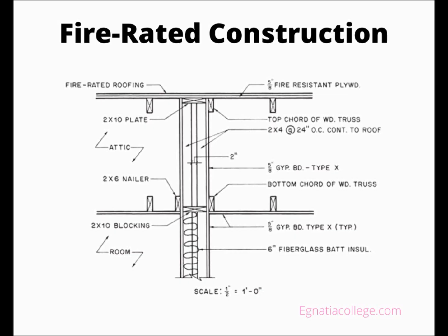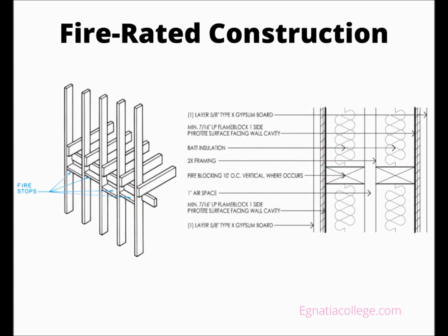To separate the housing units, a fire-rated party wall should extend all the way from the foundation to the roof. Most building codes allow an alternative to extending the party wall through the roof. The fire-rated construction may end at the bottom of the roof, as long as the roof is a fire-rated construction. This usually means that the roofing material resists fire for as long as the party wall does. For example, if the party wall is required to be a 1-hour code wall, it resists fire for 1 hour. The roof must be covered only with material that also resists fire for 1 hour.